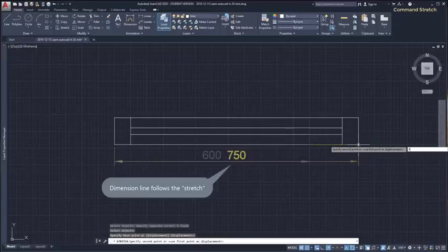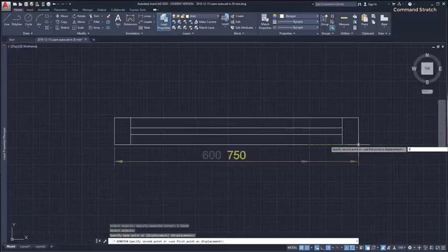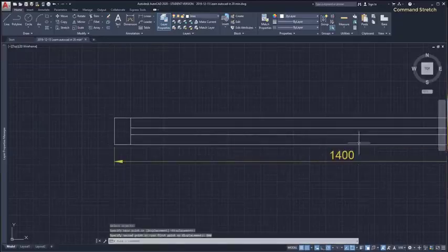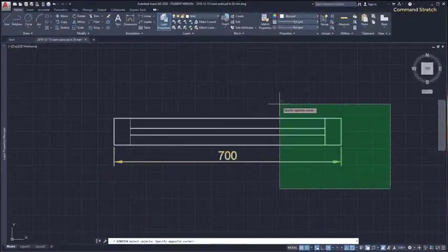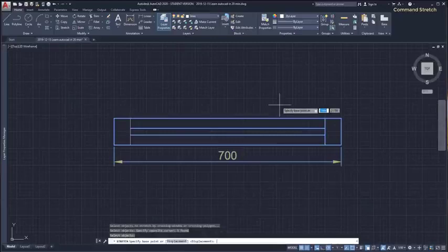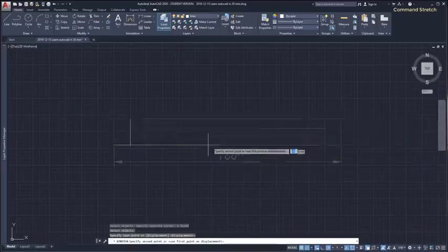Now, I can click to place the objects exactly how it's on the screen, however it's without any kind of precision, or type a distance to extend. If I type 800, actually, I add that value to the original length of 600, and the total is 1400. The way that the objects stretch depend only on the selection. Even if I select a different base point, the result is the same.